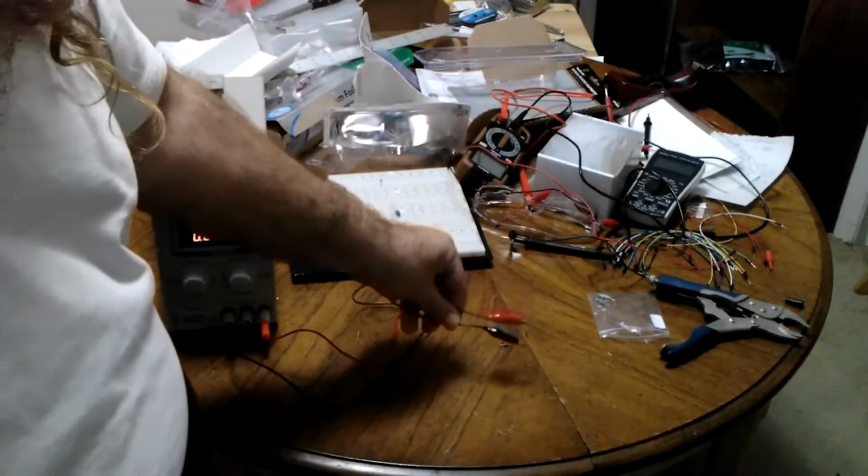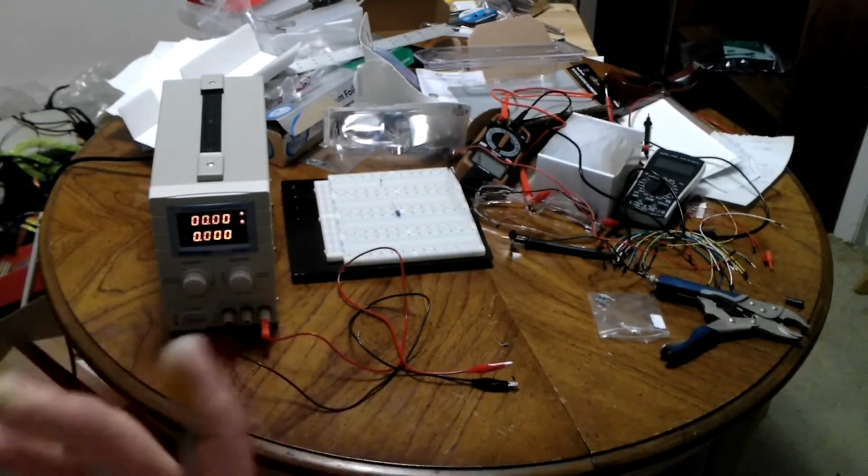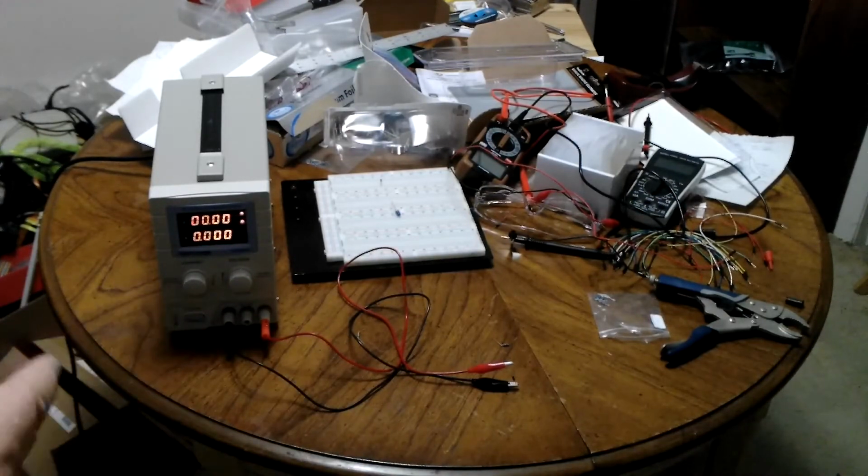And presumably, if I left it on there at 2 to 3 amps, it would have perhaps burst. So you can see sometimes you get a different failure profile based on whether you're getting a quick short circuit from something else in your circuit blowing, or whether you're just going overboard. So there is certainly wiggle room in the maximum power of the resistor.